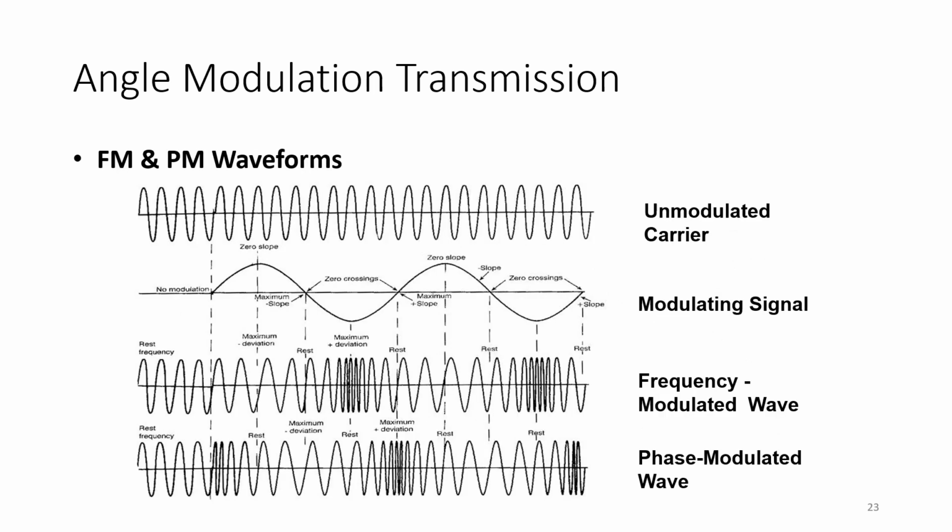Okay, so the figure illustrates both frequency and phase modulation of a sinusoidal carrier by a single frequency modulating signal. So this is somewhat identical except for their time relationship. As you can see, what will be the difference between the frequency modulated wave and the phase modulated wave? We have here the unmodulated carrier. Look at the waveform. Usually the carrier is the one which has higher frequency, and our modulating signal is the one which has lower frequency. In this case there is no modulation, so what you can see is just the carrier, both for the FM and the PM here.